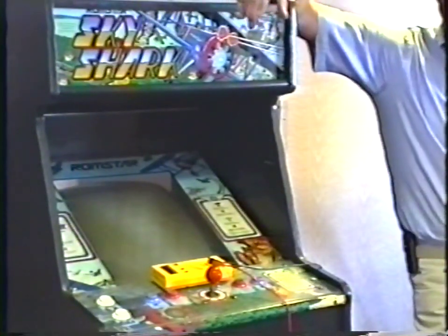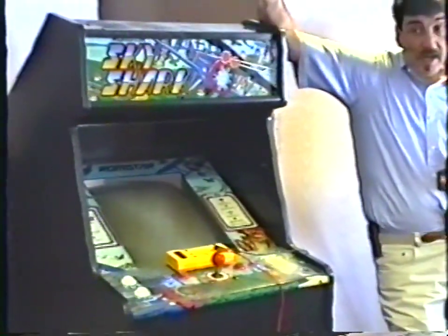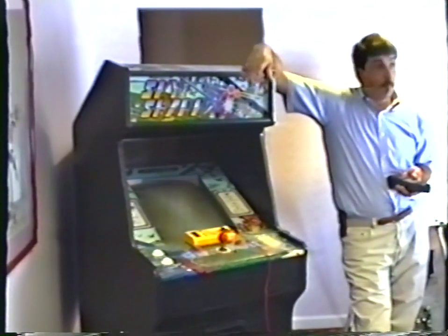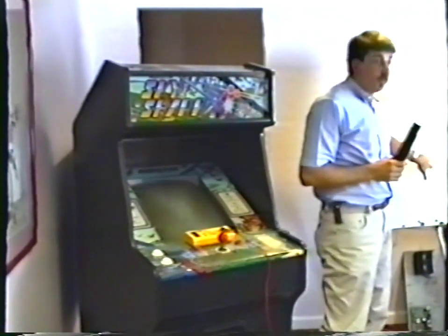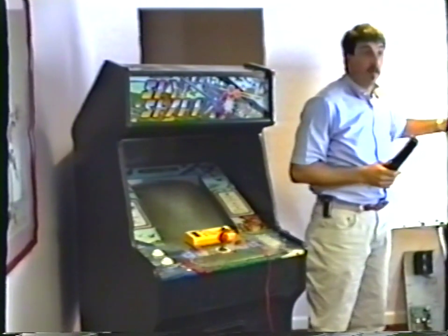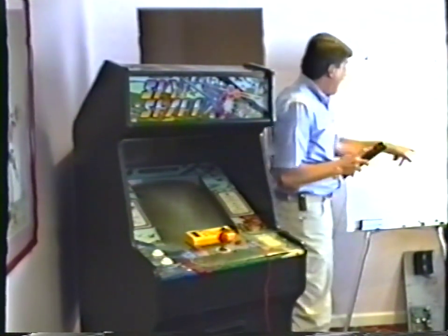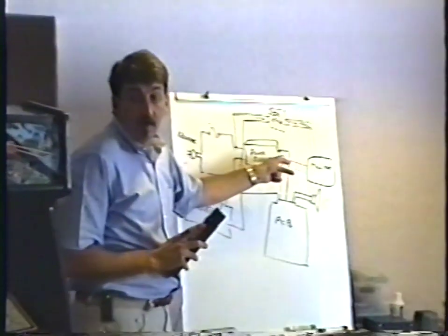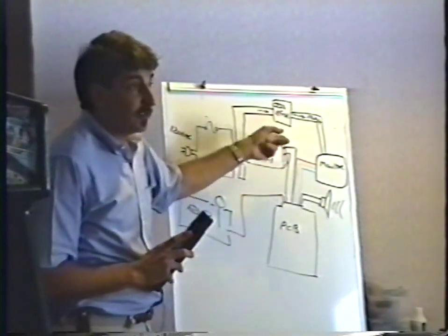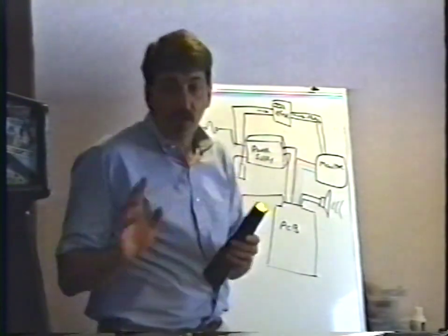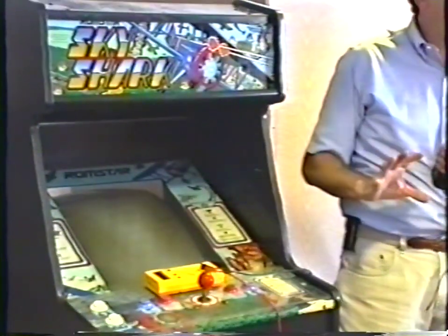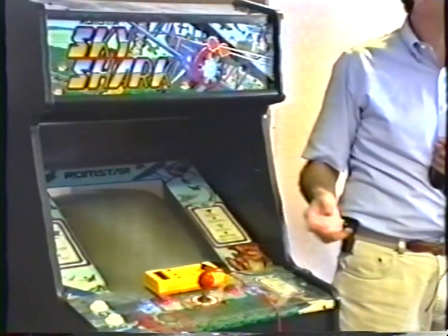See if you hear all the game sounds. If you hear all the game sounds, that must mean that the computer's working, huh? If the computer's working, the power supply's got to be working too. If the computer's doing its thing, the power supply's good. So right away, as soon as you coin it up and you hear all the game sounds, you know that the power supply is good, it's plugged in, the computer board is good.